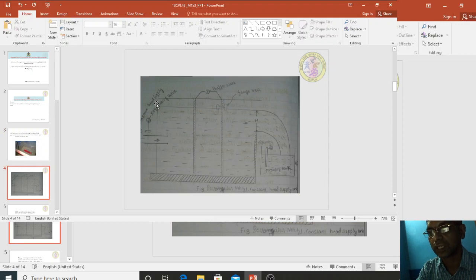So this is a cross-sectional elevation, a line diagram of the rectangular notch assembly, where this is the inlet flow, constant water supply, a regulating valve and buffer valve through which flow takes place, the gauge well, and this is the head at which flow of water occurs, and this is the measuring tank with a piezometer where we can measure the rise in water at a constant time interval.